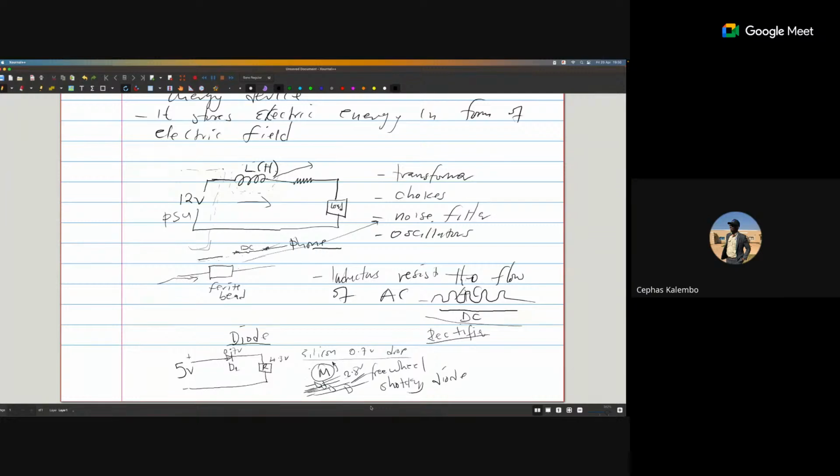So you're going to pick a perfect size of inductor after you calculate your values to put at this point, such that whenever this goes off, the inductor provides that DC. Eventually, you find that you have formed a straight line, and you just see that, oh, now I have power all the time. But in actual sense, this has been cut off, on, off, and then you have the inductor.